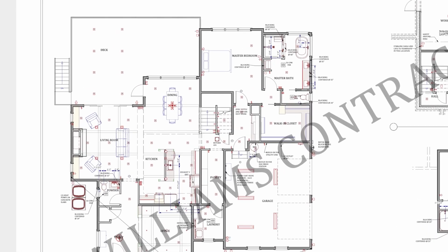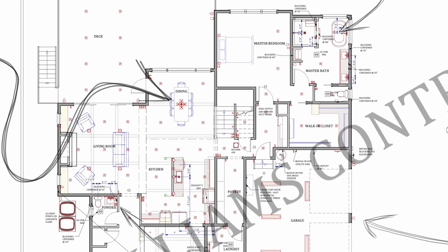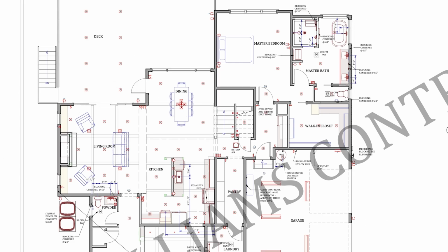In our plumbing HVAC plan, we call out center lines for each of our sink or plumbing fixtures so the plumbers know where those cabinet plans are going to line up, where the center lines are going to be. All of this information exists because when they're coming in and starting their work, all that is in place is the framing itself. This will help them understand where we're trying to center up our sinks, center up our showers, center up our toilets. Plans for the cabinets and other finishes could be modified down the road, but at this point in the process, we're going to maintain that center line call out as those designs are refined.